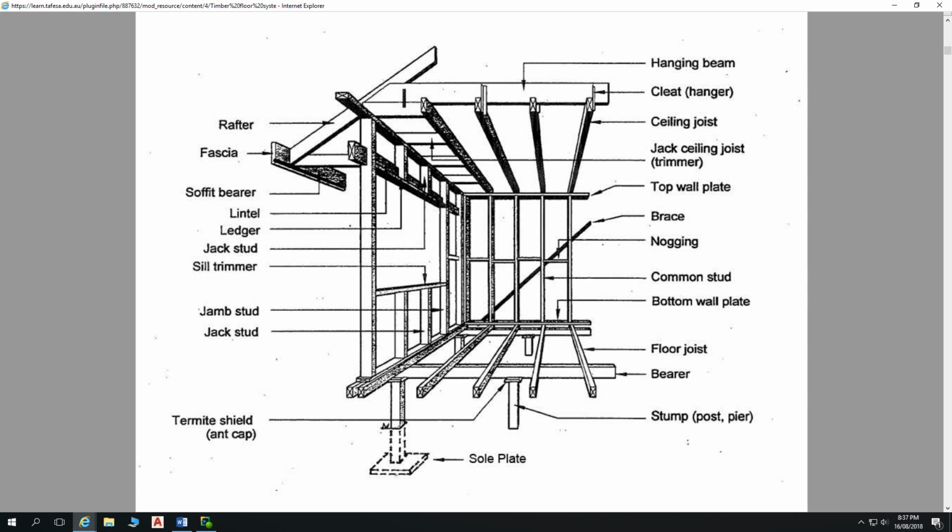With your end joists, typically you'll do double joists at the end to help support your wall frames and give you a little lip of timber for fixing your platform flooring, or your flooring if you're doing flooring fitted inside. And there are two ways of doing your flooring. One is to do platform flooring where you cover your floor first before tilting up your wall frames. The other is to do a fitted floor where your flooring material goes inside your bottom plate.